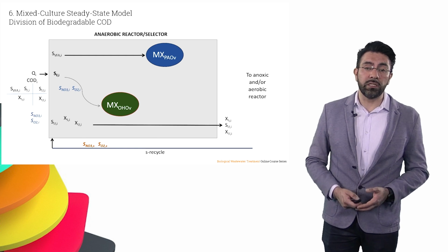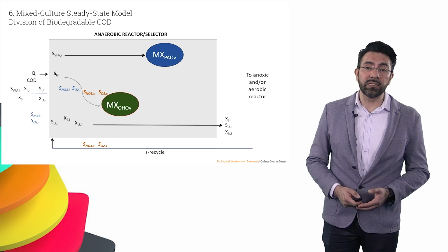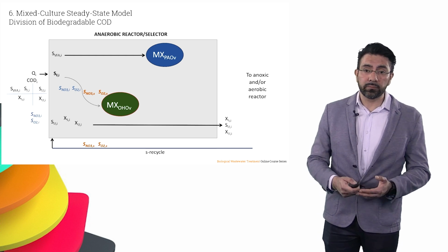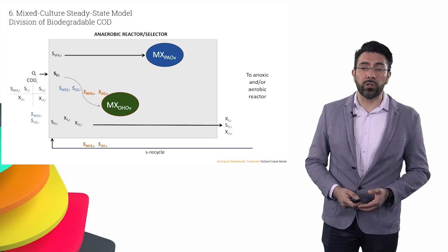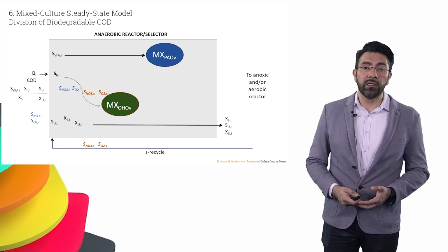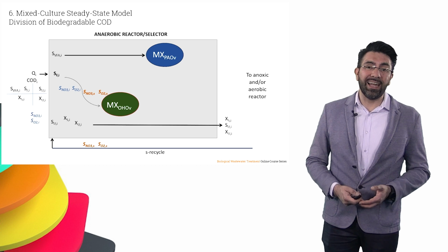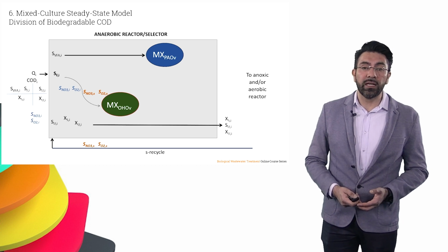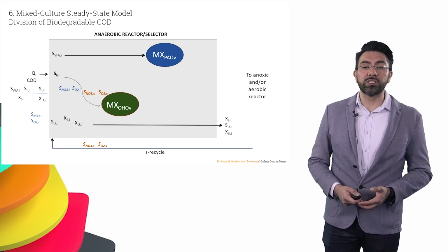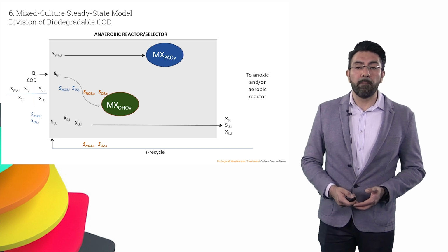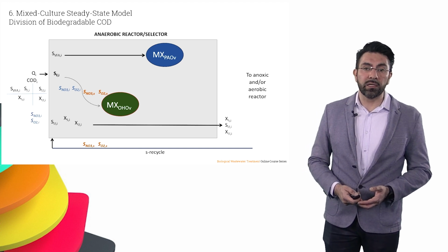If nitrate and oxygen present in the influent or in the sludge are getting intruded into the anaerobic reactor, they will not keep the strict anaerobic conditions. There will be electron acceptors that will favor that part of the fermentable COD is consumed by the ordinary heterotrophic biomass.